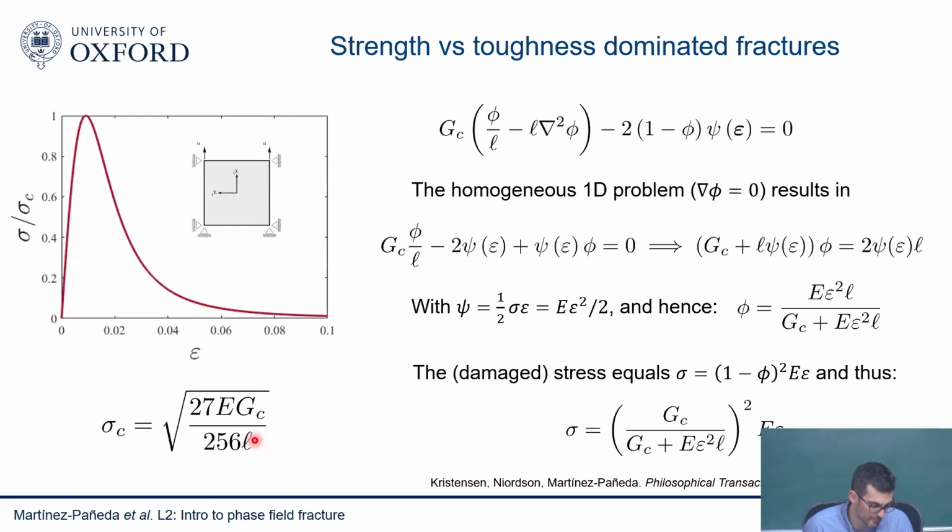Yes, so there's a bit of debate on that. It's a good point. People like Bazant would argue that fracture mechanics doesn't hold that well in concrete unless you have very large samples, because they argue the fracture process zone has a lot of extensive micro cracking. There's a bit of debate on that. I'm not going to take sides.